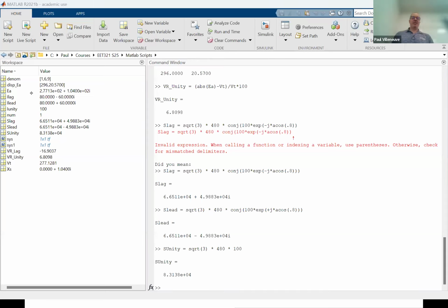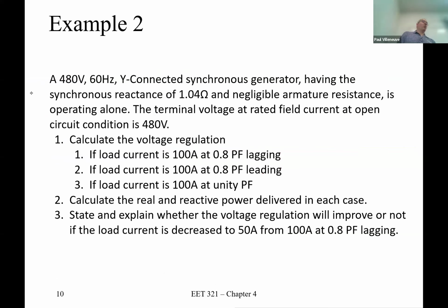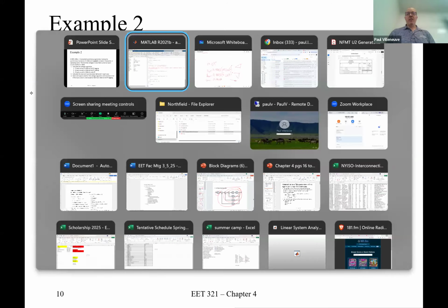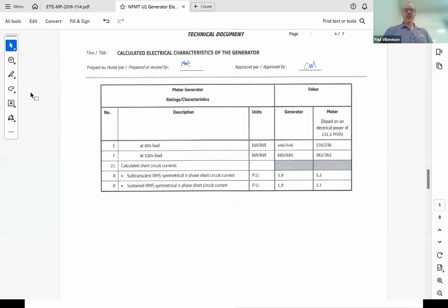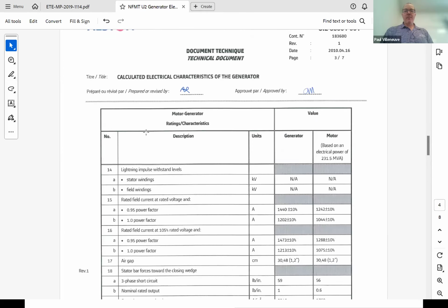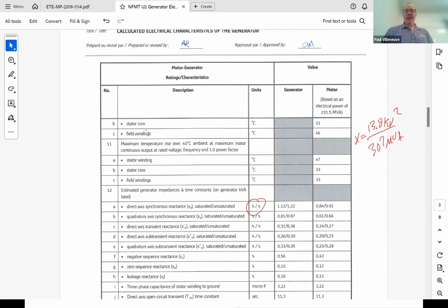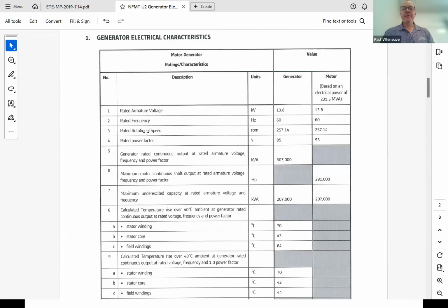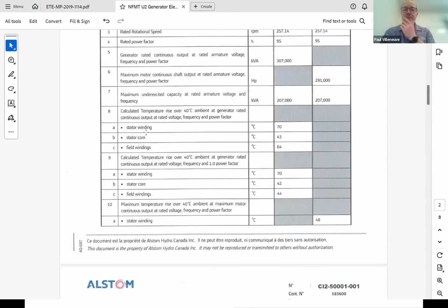Notice that's not asking the question, what does the total machine deliver? Because the machine itself internally needs some reactive power, but normally we don't worry about that. The machine is responsible for doing what it needs to do. We're just focused on what the load is. And that's why, if you look at these data sheets, remember how it said it was operating up to a 0.9 lagging power factor? Where was the value for 0.9?